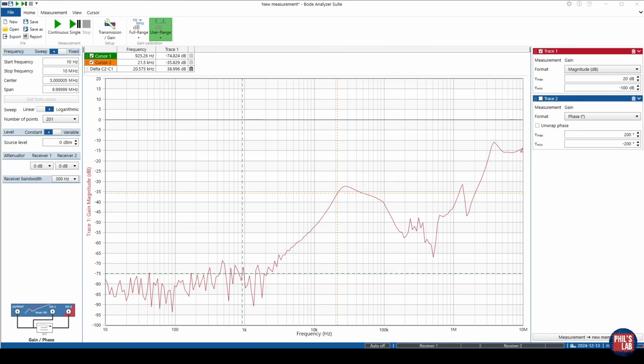Minus 80 dB, if we apply a 1 volt AC signal, theoretically, we would get only about 100 microvolts at the output, which is pretty good. However, as we go past 1 kHz approximately, we can see the power supply rejection ratio getting worse and worse. So for instance, already at around 10 or 20 kHz, we can see we've reached close to minus 30 dB of power supply rejection ratio. So suddenly for a 1 volt AC input signal, we might be getting something like 30-ish millivolts at the output.